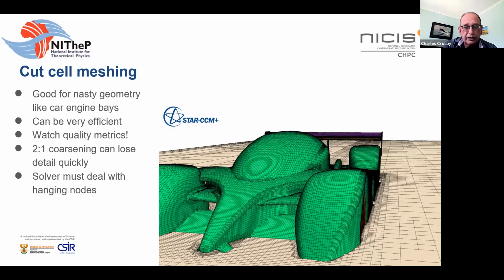And in some ways, it's a very nice method to work with, because you can start off with a block of mesh, and then you just start inserting things. And the method cuts out the bodies intruding into the flow domain, and then it snaps the grid cells onto that surface.